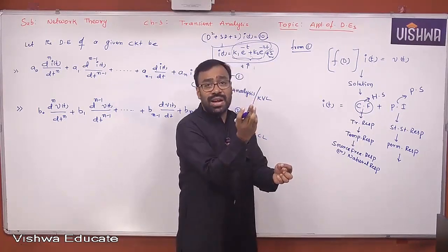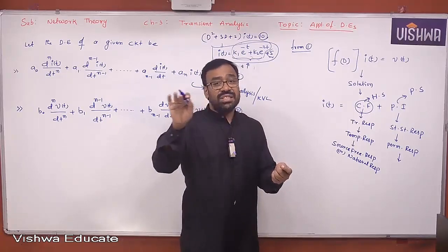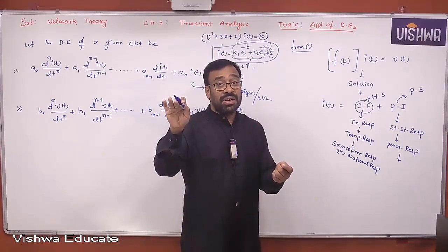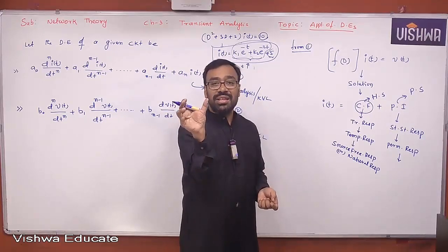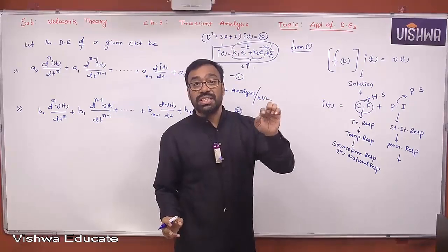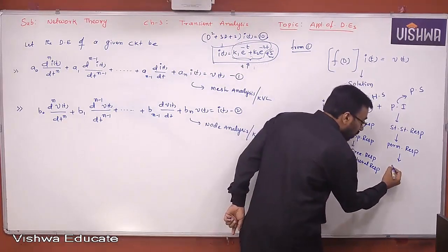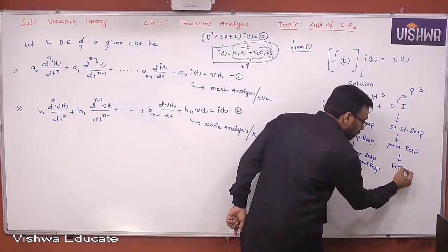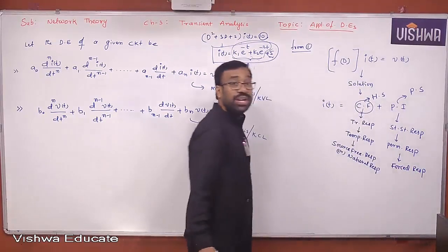It entered into the transient state where that response is changing with respect to time. And finally it reached 1000 RPM. That is another equilibrium state or steady state. Yes or no, all of you? Okay. So that steady state appeared. It's all because of the given force. That is nothing but you have given some input. Therefore, this response is called forced response. What is it called? Forced response. I hope you understand the point.